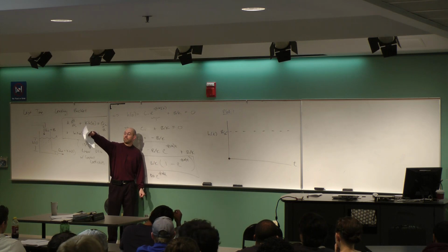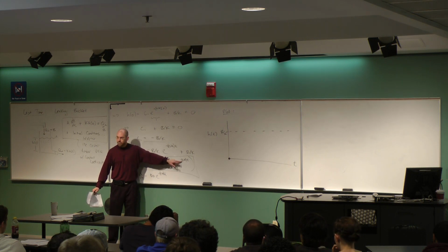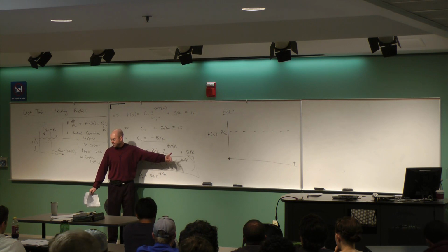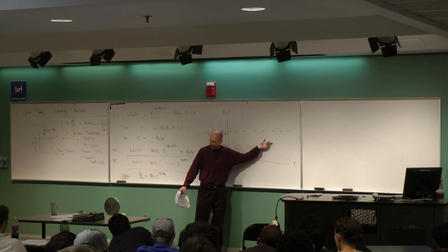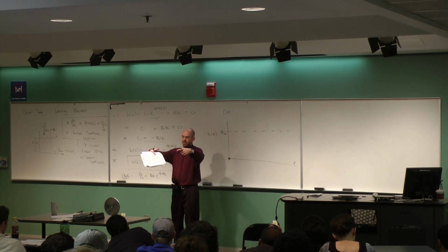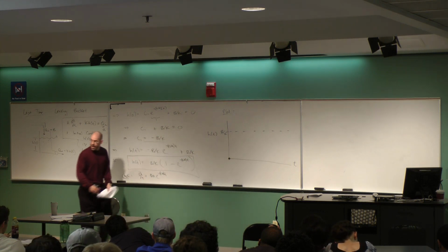Time equals a over k. Sure. What about when t equals a over k? Then this is e to the minus 1, right? What would be another number? 2a over k, 3a over k, 4a over k. The time over which this thing transitions to the steady state depends on a over k. Think about it. How big's the tank? How big's the valve at the bottom? This controls the time behavior of the problem. And so I want to use values of a over k.